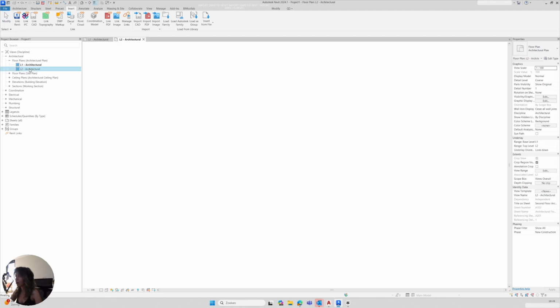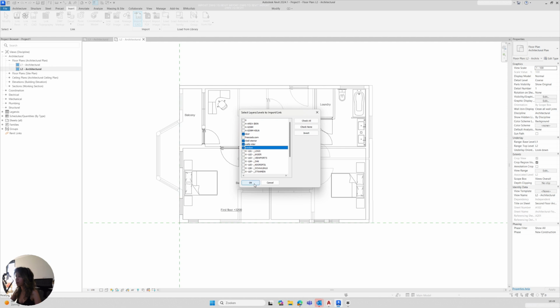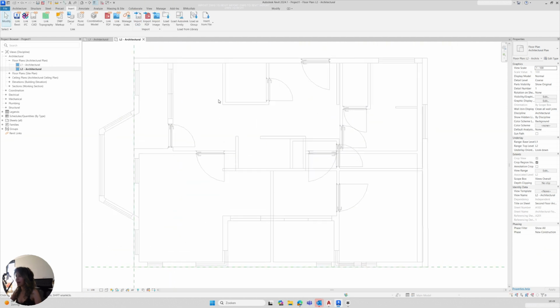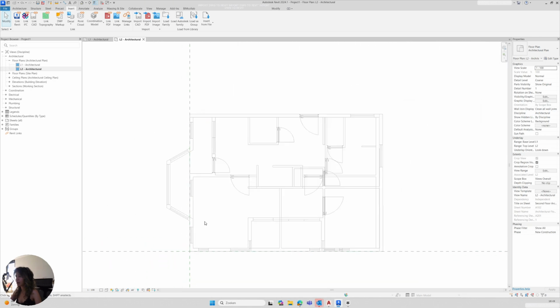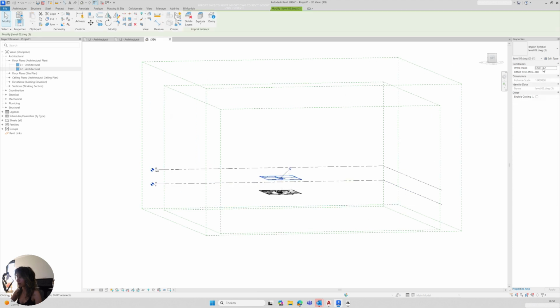Then I open level 2, second level, do the exact same thing, Windows, okay. There you go. I got my second level on the correct spot. Check the position of each layer. For example, here you can see in properties, work plane is level 1 or level 2. You can easily switch levels, send it to other levels.